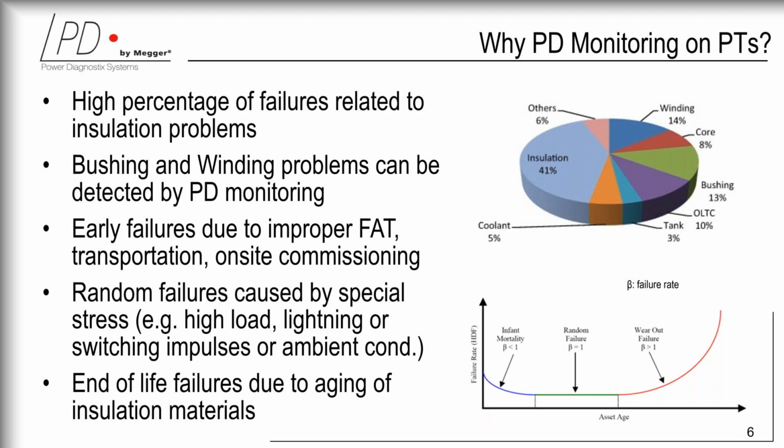And how do we do that? Generally speaking, we can look at partial discharge monitoring. This is happening right after the transformer has been built, may not even be filled with oil yet, and partial discharge is being tested at different levels, even on components. And of course, after that, you go through very complex tests.